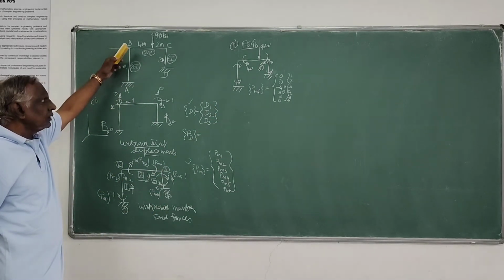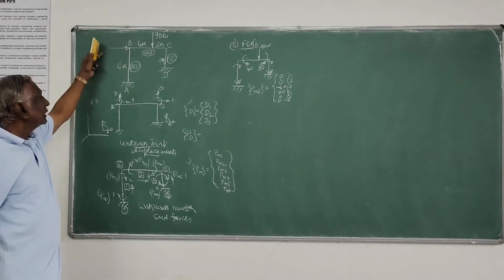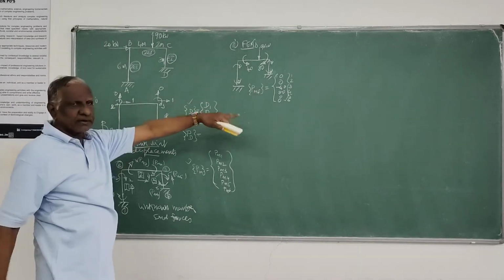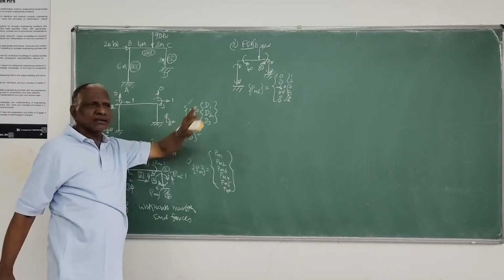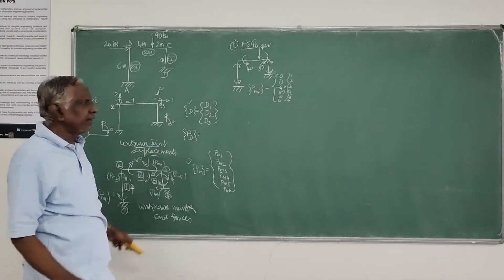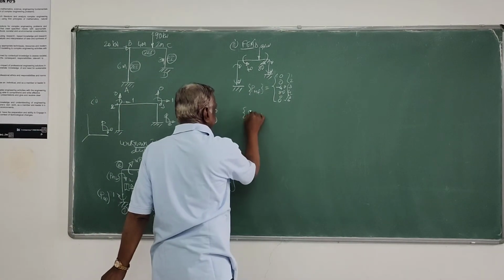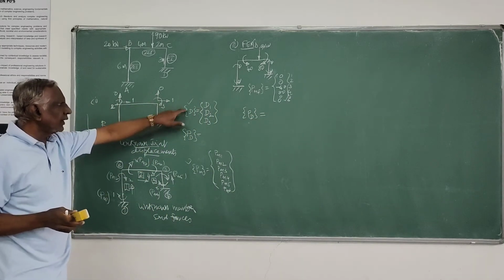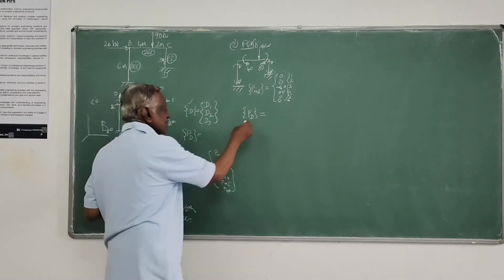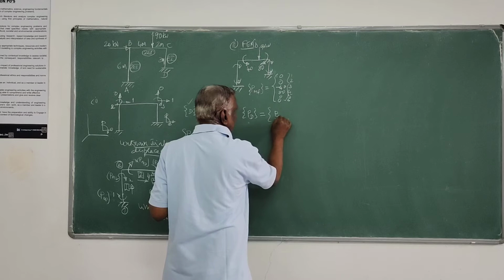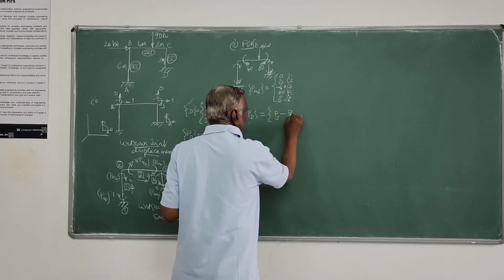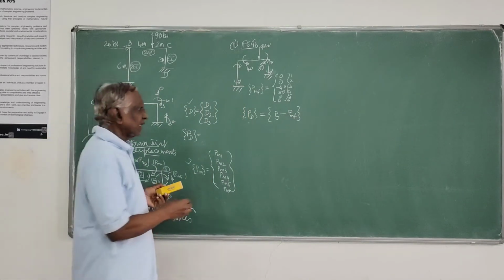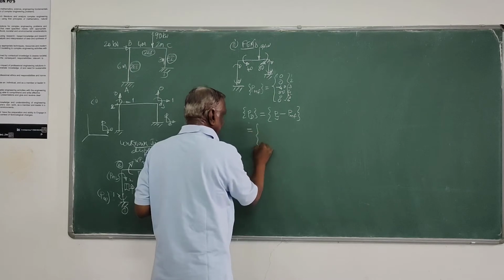And we have a joint load here, acting horizontally. This load we can take as 20 kilonewton, and that we have to subtract from this PMF in order to get this PD. Next, this PD we will generate, that is the load corresponding to unknown joint displacements. This is nothing but the joint loads corresponding to the unknown displacements minus the fixed member actions. So we will take it like this.